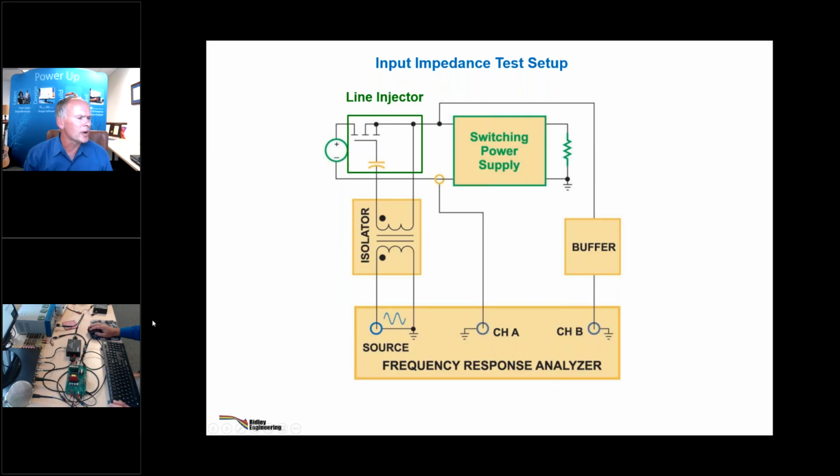One person asked about shunt through measurements. I don't know what all that is, but this is the way we do it in the industry. We've always done it this way for 40 years, and it's not going to change. There are no shortcuts on these measurements. On the loop, you've just got to get in there. If it's a loop and it's breakable, do it. And if it's not, then you do the best you can with these impedance measurements.